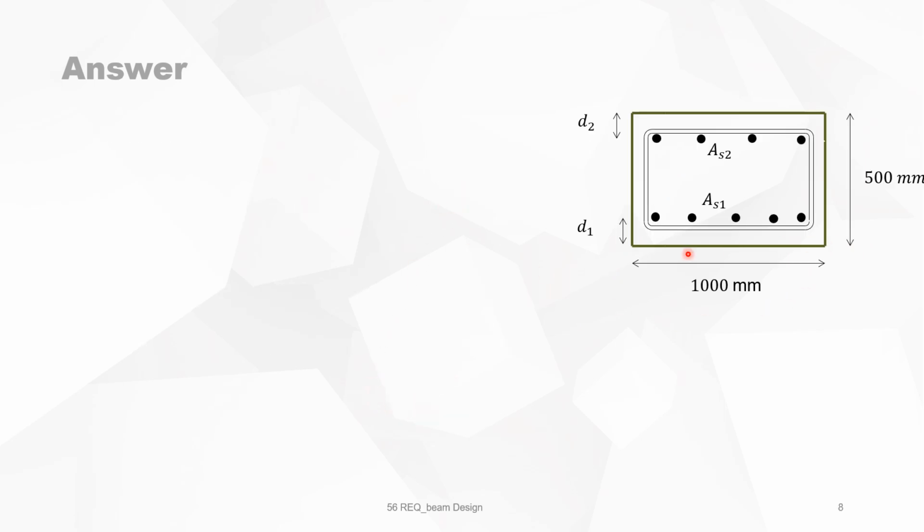So we have the beam, 1 meter width, 500 millimeter in depth, with the reinforcement. The compression reinforcement is then the tension reinforcement times the ratio of the stresses that we've calculated. We know now 435, 436, it will not give a big difference, but just to give you a complete picture of how to calculate it, I've written it down. So it's 3,779, in itself 3,770.